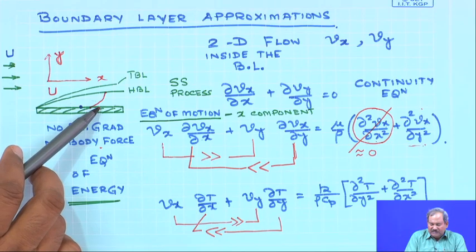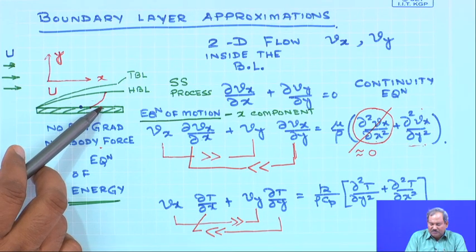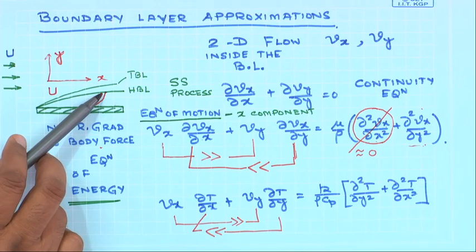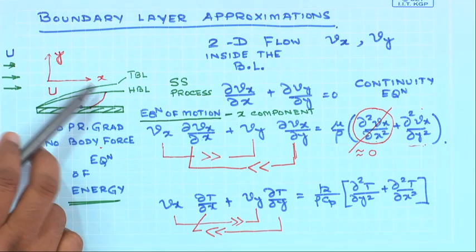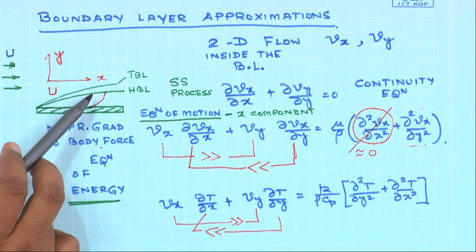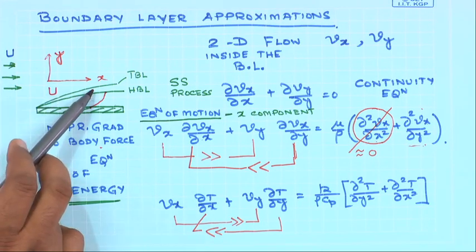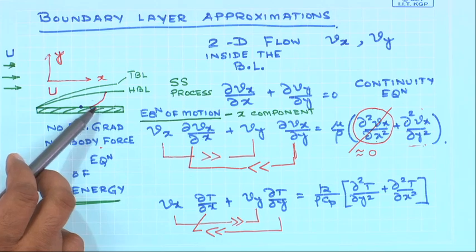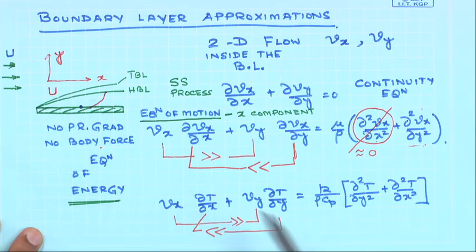So T changes from Ts, which is the surface temperature of the substrate, to T infinity, where T infinity is the temperature of the fluid which is flowing over the flat plate. Since the thermal boundary layer is small in thickness compared to the overall length scale, del T del y would be much more than del T del x,